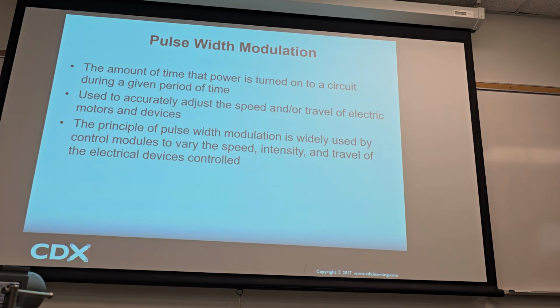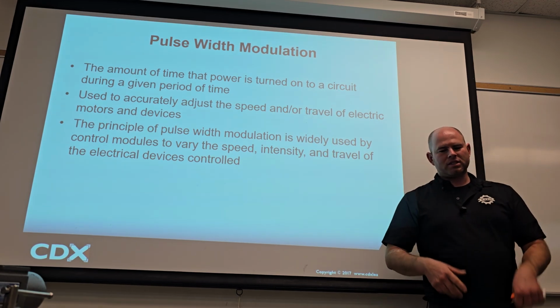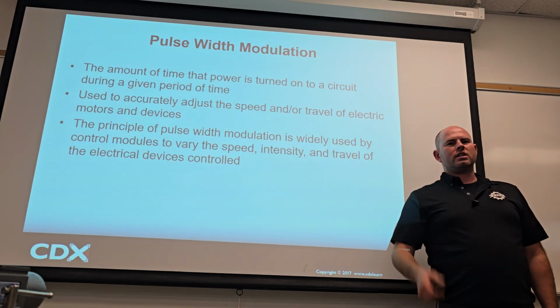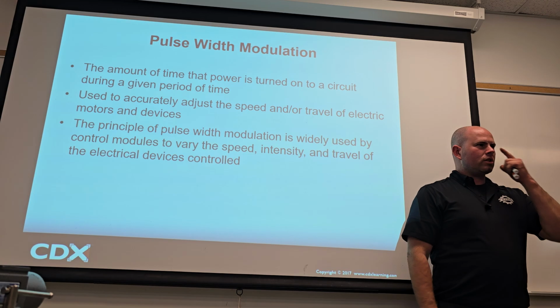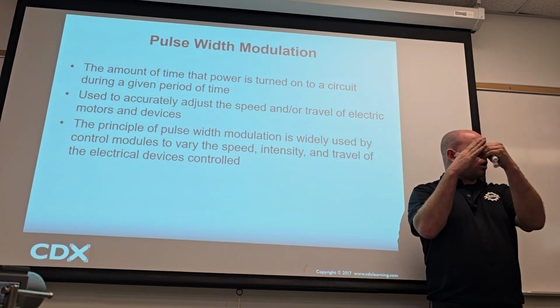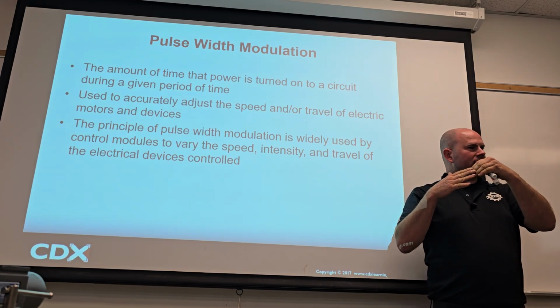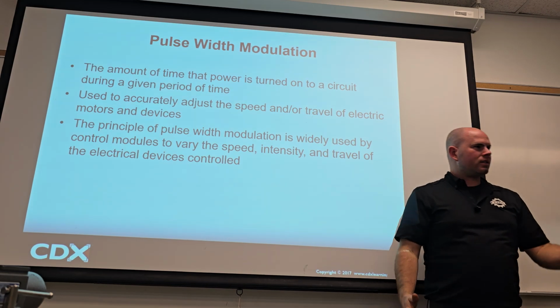I probably could have guessed a new fuel pump, because it would intermittently blow the fuse, but only on startup and only about once every 8 times. So I'd be cool for a week or two because I didn't ride every day, and then I'd go to start it, boom, and it wouldn't start. I'd jump out, pop the seat off, the fuel pump fuse was blown, I'd put a new fuse in, and I'd be good to go for another week or two. It was a weird issue, almost like there was an arc happening on the wire, but I looked at the harness and it checked good.